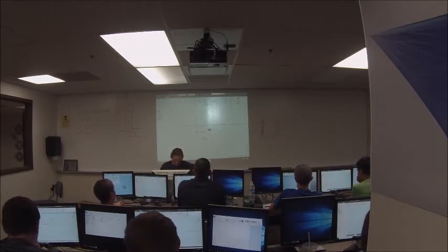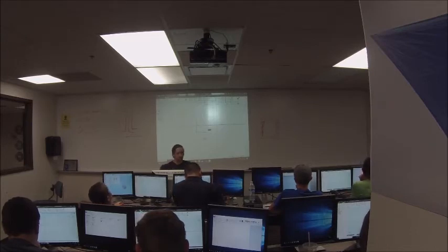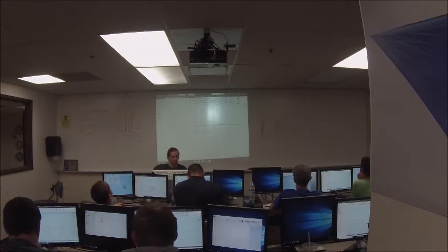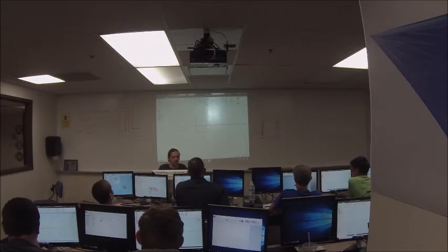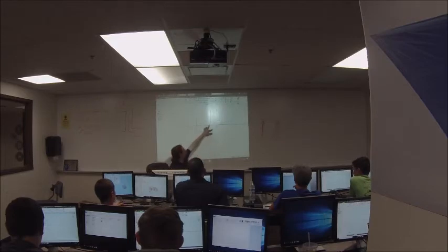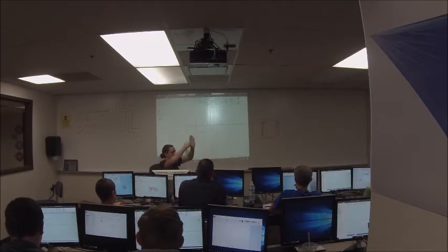It will also place, well, obviously it places coincident constraints. This corner, these two lines are joined by a coincident constraint. So if I take two separate lines that aren't attached, and I want these two lines to attach, I can click the coincident constraint, click one endpoint, click the other endpoint, and you see they snap together.